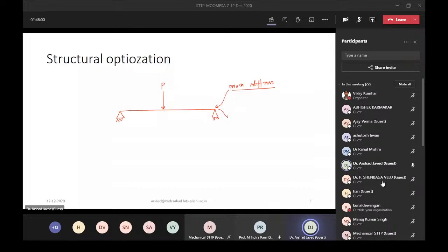And shape and size directly refer to the amount of material used. So if you wanted to make it more stiff, we can increase the depth, we call it T. This we can increase. The width of the beam can also be increased, okay. Length remains constant, and you can keep on increasing the thickness. But up to how much extent? Up to where we can go? What is the maximum value at which we can go?